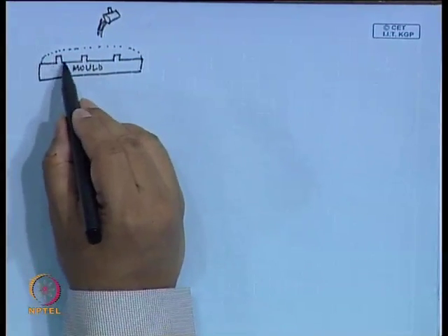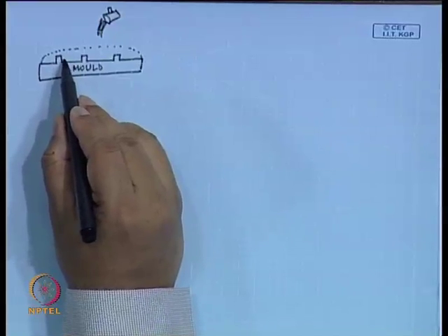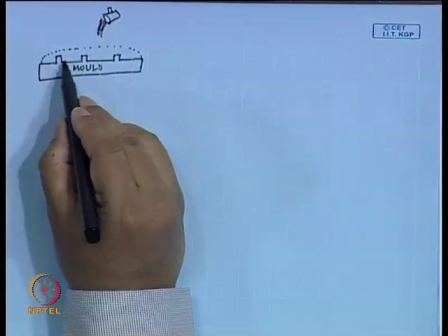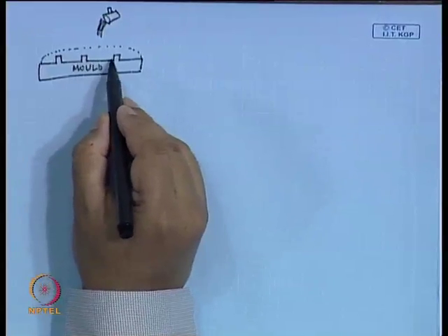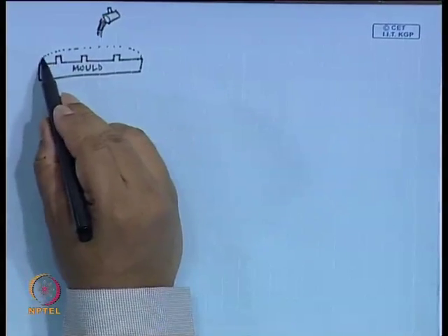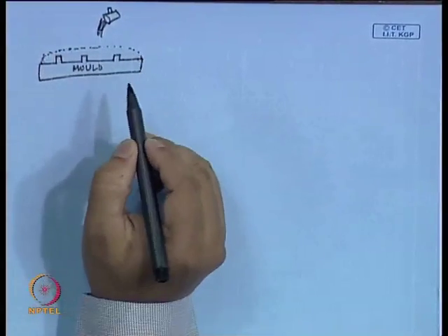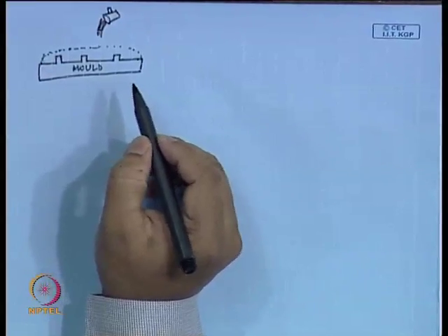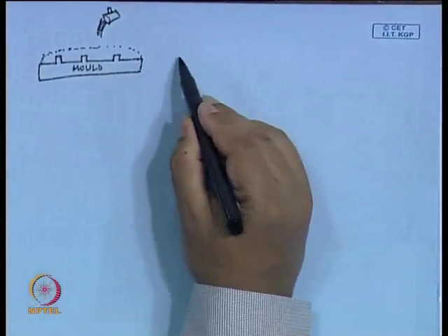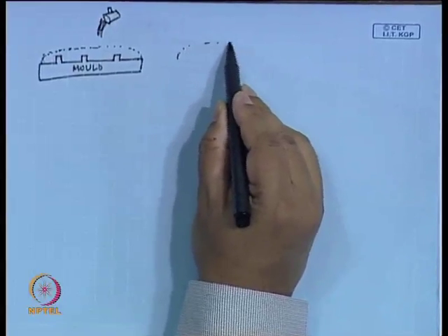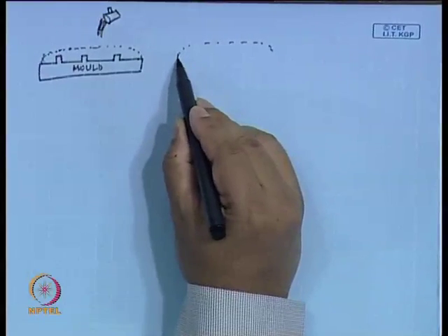You heat the mold as well, so that if there is a tendency for the polymer to solidify in the corners, you will ensure that the polymer flows everywhere to all the corners, okay, and it forms a layer. Okay. Then the structure is peeled off the mold and contains the pattern of the mold in negative form. So, when you peel it off, how will it look? The upper portion, if you peel it off,